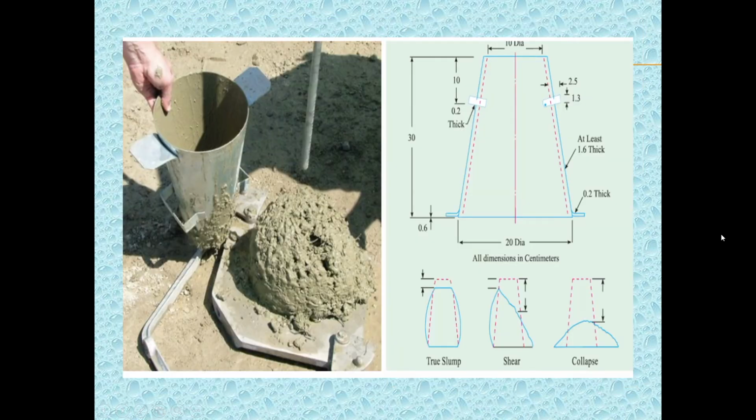There are various patterns of slump. It indicates the characteristics of concrete in addition to the slump value. If the concrete slumps evenly, then it is called a true slump. If one half of the cone slides down, then it is called a shear slump. In this case, the slump value is measured as the difference in height of mold and the average value of subsidence. It also shows that concrete is non-cohesive and indicates segregation characteristics. If cone spreads, then it is called a collapse slump.